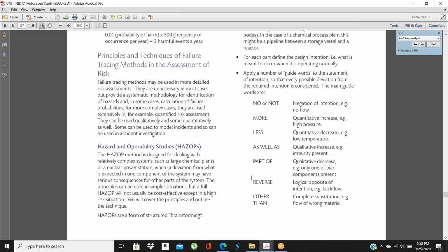First of all, we will divide the system into different parts, which are called nodes. After that, we will identify the hazards with each node, and then we will provide the controls. This is a simple 3-4 step process. Okay, and we will check the temperature, the flow rate, and the pressure. Let's suppose if it increases, if it decreases, there is no pressure, there is no water flow, and what the root causes for that are, we will discuss in this study.